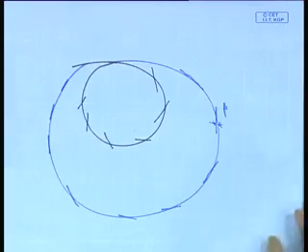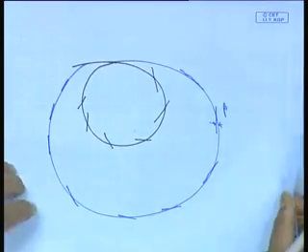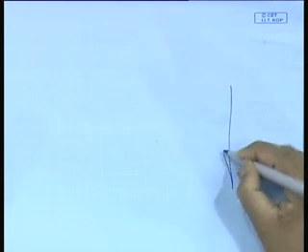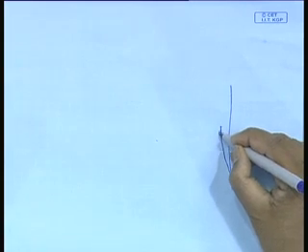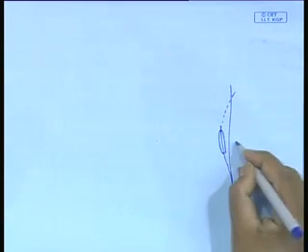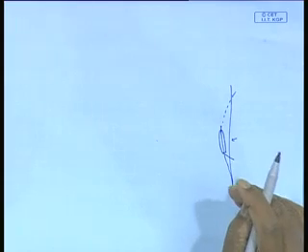Now, we will look into this behavior part of why initially the ship has turned on this side, and what is the role of the hull along with that. Let us look at that. Initially I mentioned that as the ship goes, it basically goes this way. In the first phase, the approach phase, it has actually gone to this side, even though I have given rudder here.